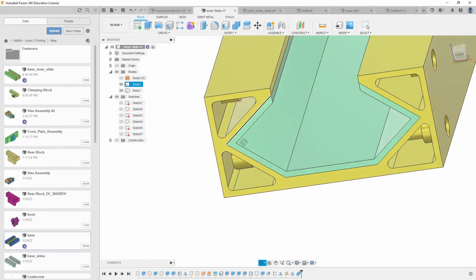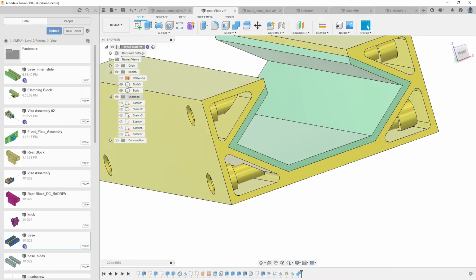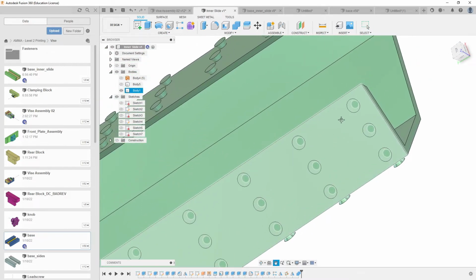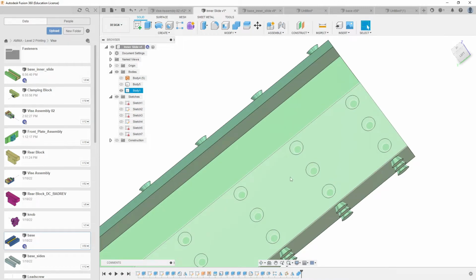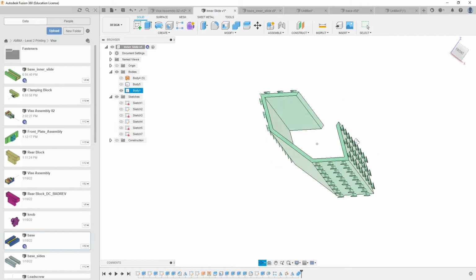You could elaborate on this a lot if you wanted to. So for example, if you felt that maybe the edges were still coming undone, you could do a lot of work to this. You could have a whole bunch of little dots here, but you might just run a sketch right along the edge right here, just a real thin, like maybe 1 or 1/2 millimeter of a lip here, draft it out so all of your edges are embedded into the other part as well, you see?